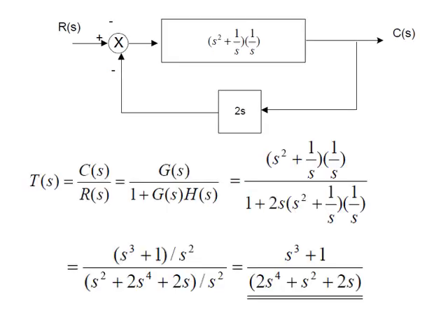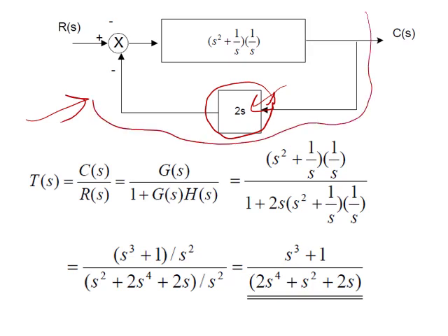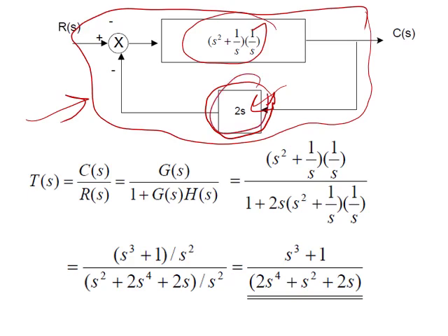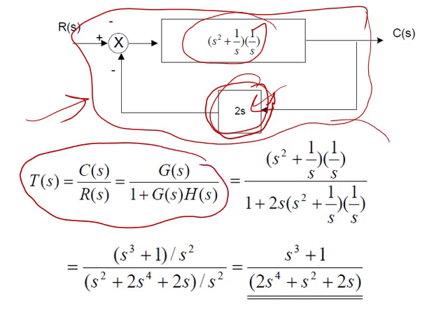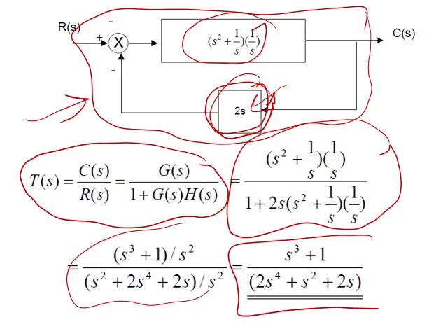So here he did it the same way. You see, he added those two, S and S, and it becomes 2S. And the system looks like this now. It's very clear that the remaining part is just a feedback as you see here. So this block with this block can be joined together with consideration for the feedback rule as you see here. So substitute the values, reduce, further reduce, and finally this is the transfer function we are looking for.